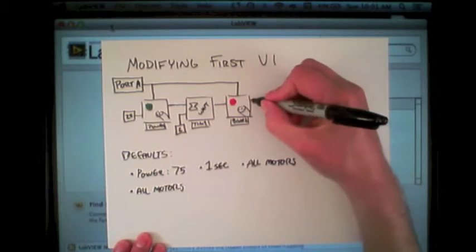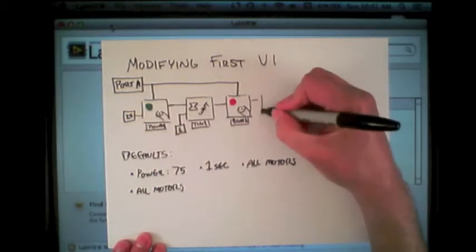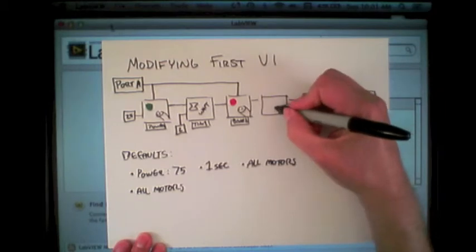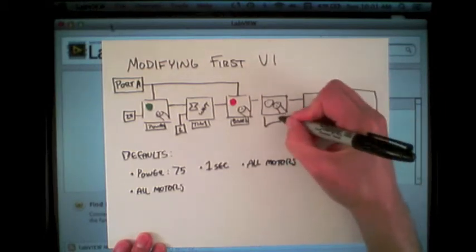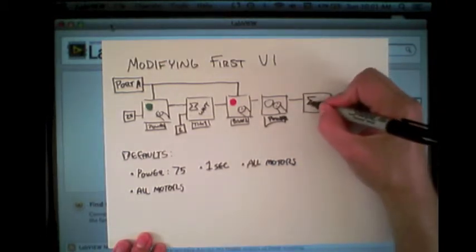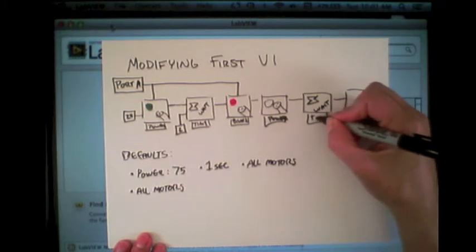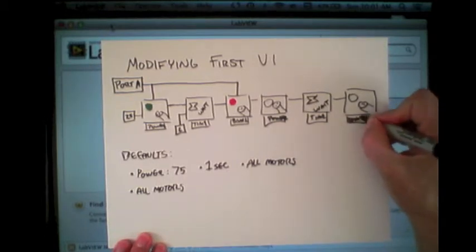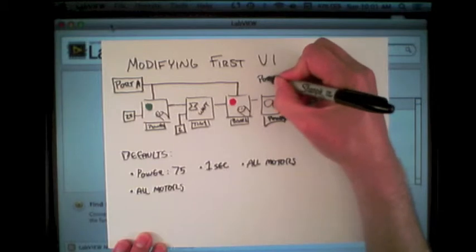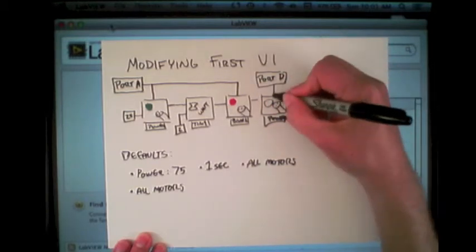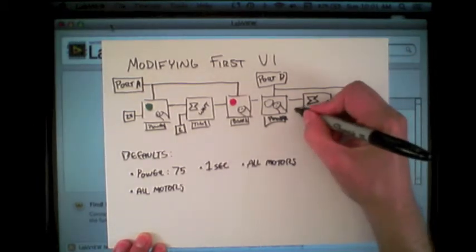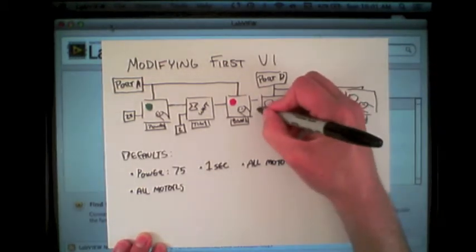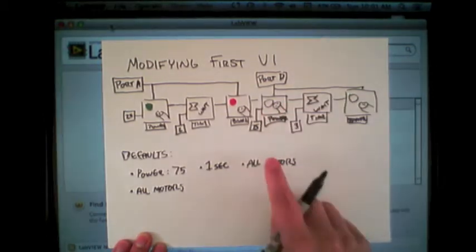The second thing that we'll show is that you can also copy and paste your code to duplicate it and increase your program. So here what we'll do is we'll increase the start motors. We will do a second wait for time, and then finally a second brake. But this time, instead of port A, we can change it to, say, port D and control a second motor instead, and perhaps do that for 3 seconds instead of 2. And if we copy the code, there'll still be the 25 there for the power.